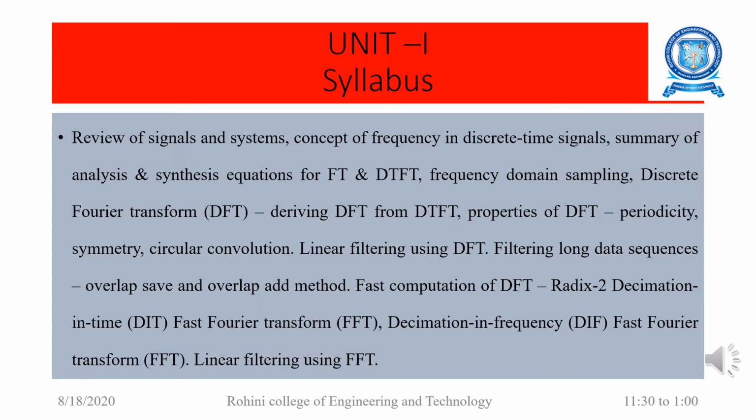Then we study periodicity, symmetry, circular convolution, linear filtering using DFT, and then filtering long data sequences. So we filter long data sequences using the overlap save or overlap add method, and fast computation of DFT using radix 2 decimation in time fast Fourier transform. We simply say FFT, or decimation in frequency fast Fourier transform, and linear filtering using FFT.